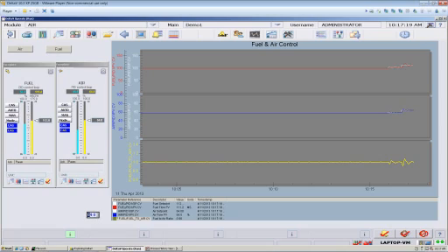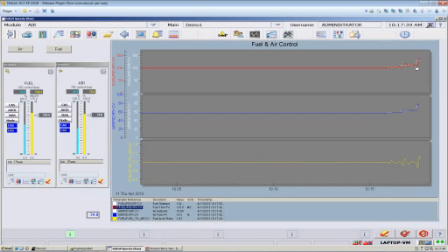Continue that same example of bigger and bigger changes. Now, a 10% change rather than a 5% change. Let me highlight this red trace so you can see a little bit easier. You can see by design with Ziegler-Nichols tuning, these overshoots are about 50%. So this height is about 50% of the initial change. This dip is about 50% of that. Eventually we settle in, but at the expense of our ratio wasn't very good through this.